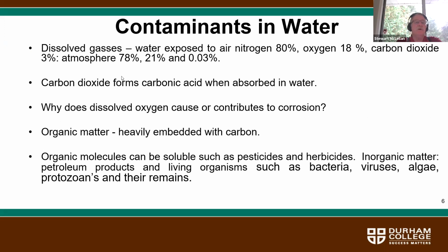Okay, contaminants in water, dissolved gases. Water exposed to air: nitrogen 80%, oxygen 18%, carbon dioxide 3%. In the atmosphere, 78, 21 and 0.03% of those gases. Carbon dioxide forms carbonic acid when absorbed in water. So there's a couple of questions coming up here.